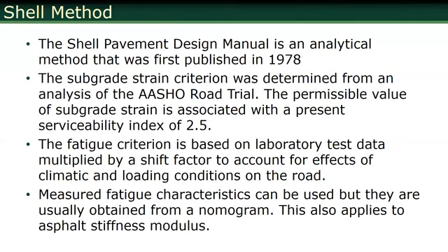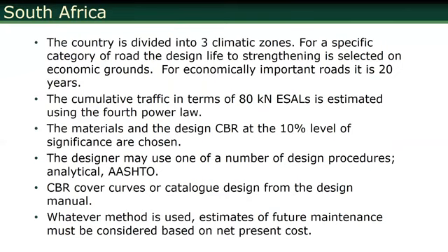So the Shell design method is essentially you use a structural analysis program to find stresses and strains at the bottom of the asphalt, and there's an equation that relates number of cycles to failure to the strain that you have there, and that particular equation is calibrated, quote unquote, calibrated to the AASHO road test kind of a thing. South Africa is again based on the AASHTO procedure, and there is basically ESALs calculated from an 80 kilonewton load, and they have a whole bunch of different CBR values that they use in that zone.